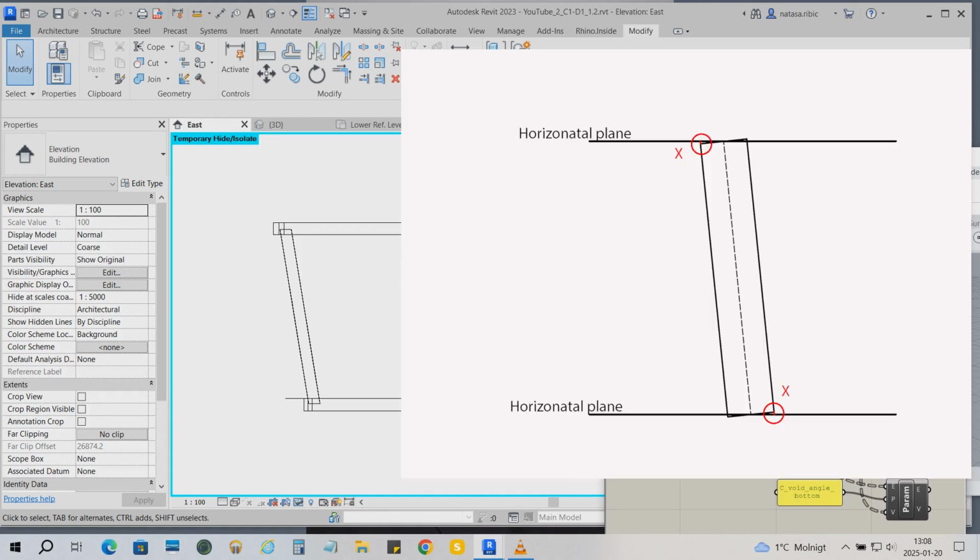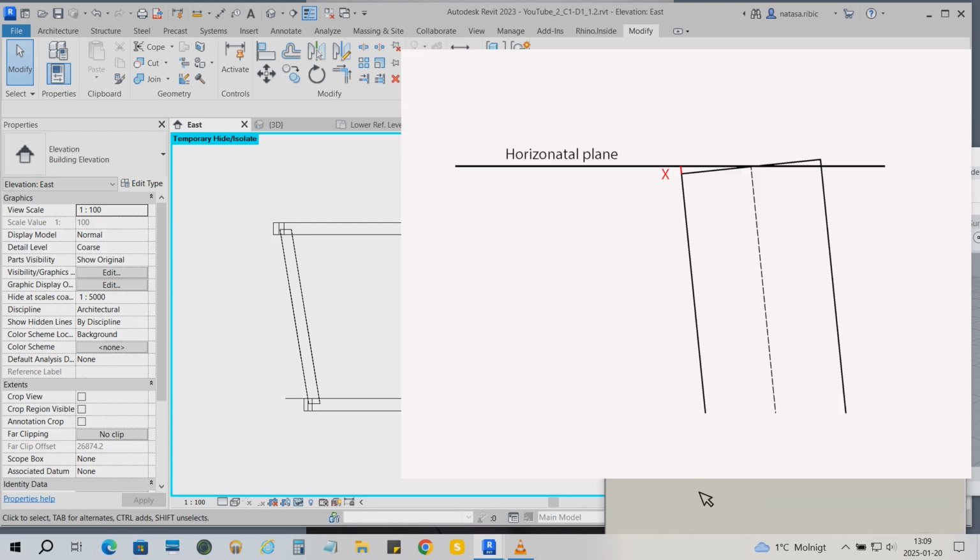You see here, the center line is going from top to bottom, and since the column is tilted, we are going to miss x value at the top and the x value at the bottom, and that's what we are going to calculate, and then extend the length of the column with 2x. And let's do that together. For the x, we have this length. This length is half of the diameter of the column.